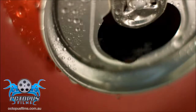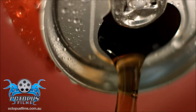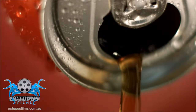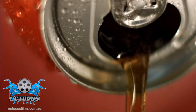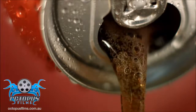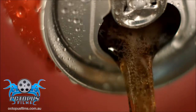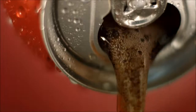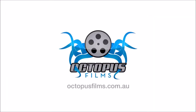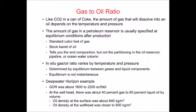So when we think about gas-oil ratio, I want to start off by looking at soda coming out of a soda can. We know CO2 is dissolved in the liquid. We've just opened this can, starting to pour out. Initially, there were almost no gas bubbles. Now, as the pressure has been released for longer, the gas starts to come out of solution, forming bubbles. And the same thing is happening in an oil as it comes from the reservoir, which is at high pressure with lots of gas dissolved in the liquid phase, and it comes up the pipeline eventually to the production rig where the pressure is much lower. That gas is going to come out of solution.